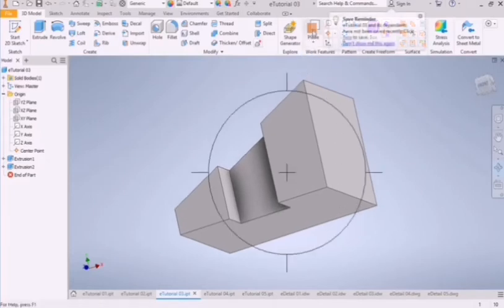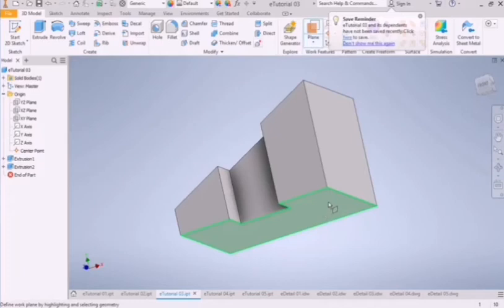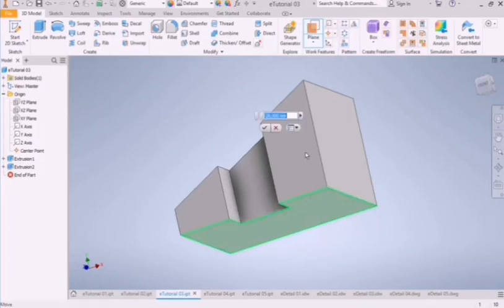We already selected the plane, and then we highlight the bottom part, and then we click. We have to click and drag. As you can see, the direction is negative. That's what we want, because if it's positive it will go to another direction, bottom. So now it's going negatively to upwards, and then now it's negative 50.